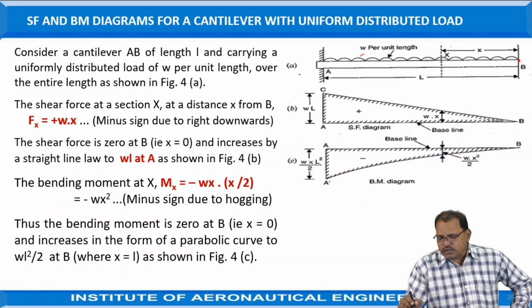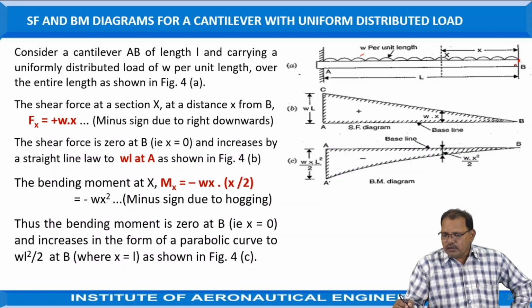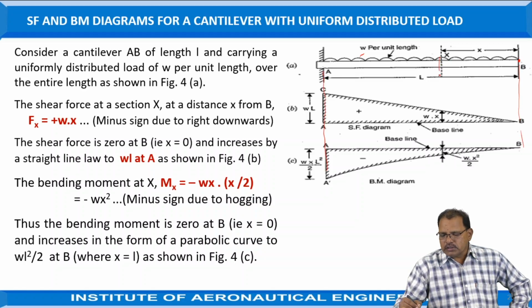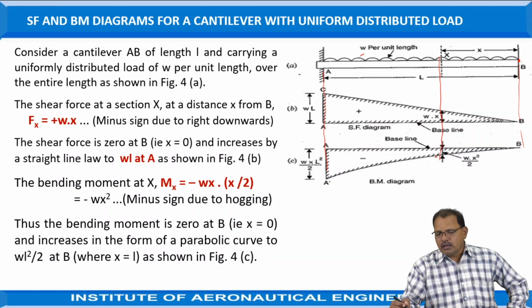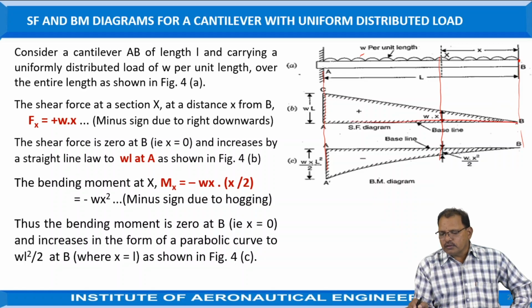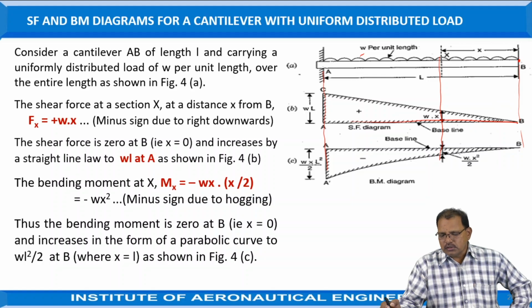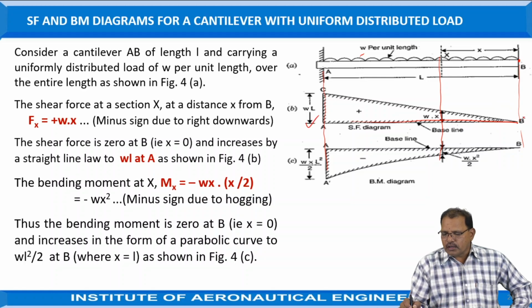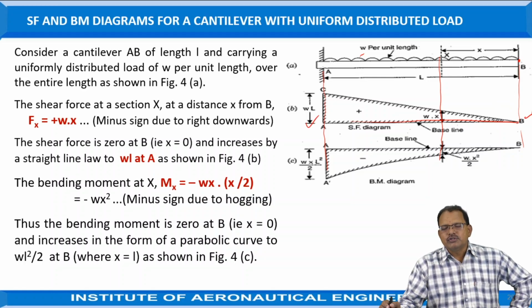Hence, in order to draw the shear force diagram as well as the bending moment diagram, first of all, draw the figure to represent the forces which are acting on it. From the end position, draw the lines as shown in the figure, and we are considering one point X. Again, draw the vertical line as shown in the figure. At a convenient length, just draw a line AB to represent the shear force diagram of the given beam. Since the shear force is positive, it should always be above the reference line AB as shown in the figure. At B, the shear force is equal to 0.